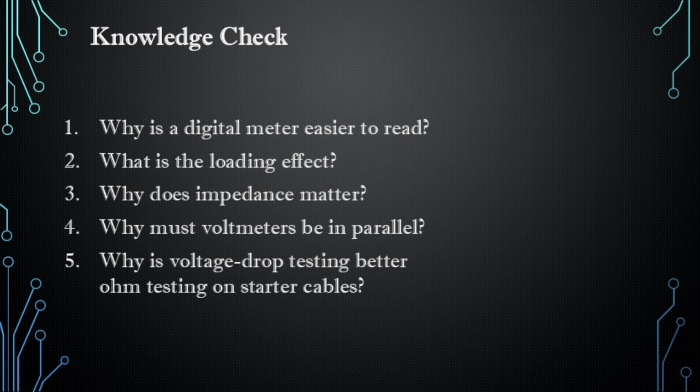Slide 15. Knowledge check. Now let's review the key points. Why is a digital meter easier to read? Because it provides a direct numeric display and reduces interpretation error. What is the loading effect? It is the condition where the meter changes the circuit enough to alter the reading.